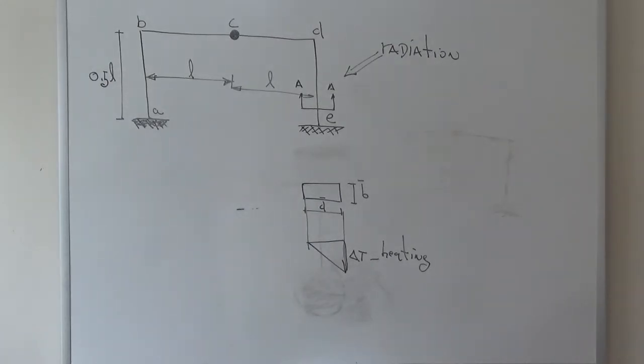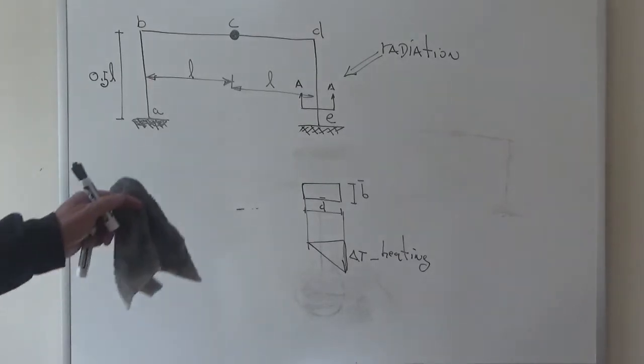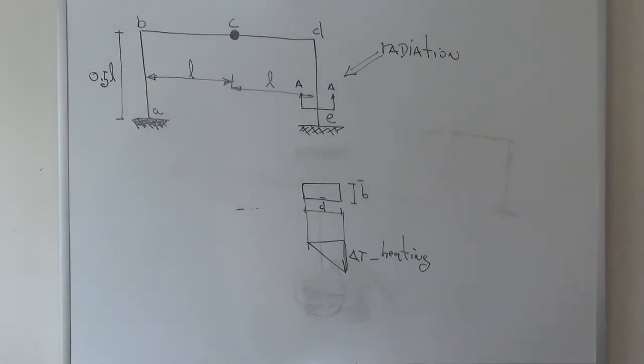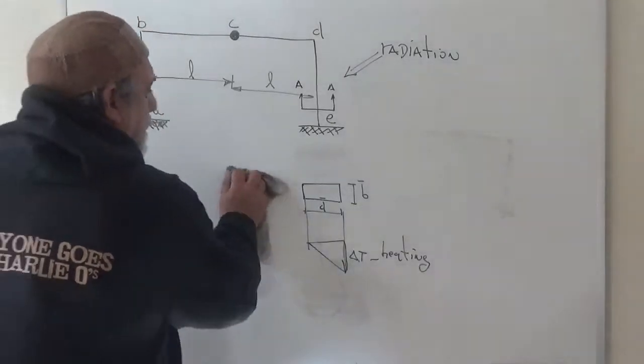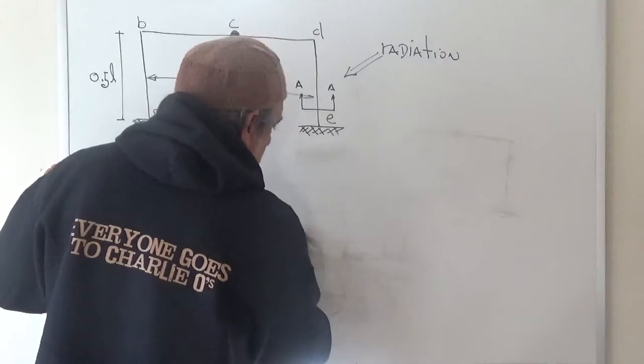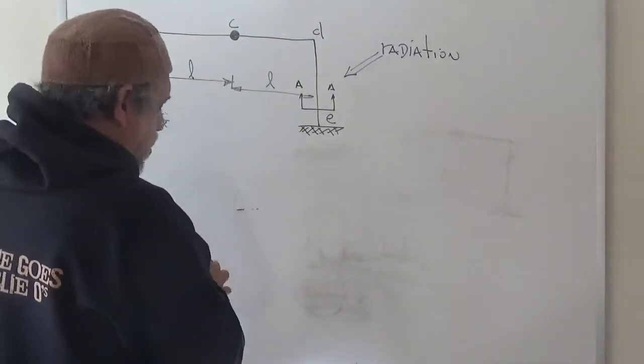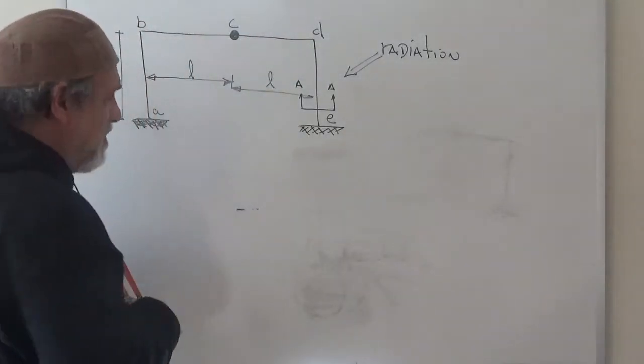In the case where the structure is statically indeterminate, this is no longer possible, and so in indeterminate structures, the appearance of a temperature change, in general, will lead to moments and shear diagrams. To make that intuitively clear, before we go to this structure, allow me a small parenthesis.